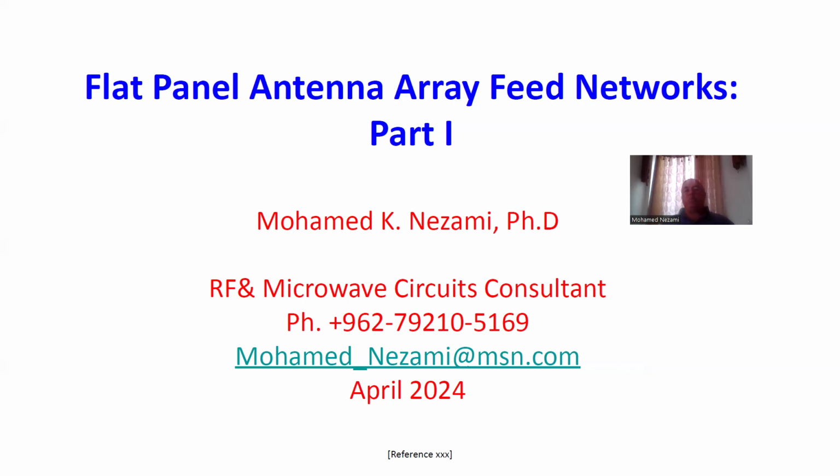The only time we use Wilkinson dividers is with the issue of the resistor, the 100 ohm resistor implementation, whether it's in thin film or thick film at lower frequency. You can't use surface mount resistors past, say, 8 gigahertz. We have to use thin film fabrication technology, and so that complicates the feed networks. That's why people turn to T-junction networks, but we have to design them correctly. The simulation modeling is good.